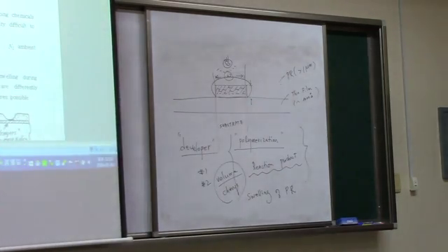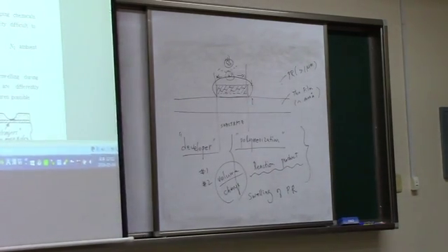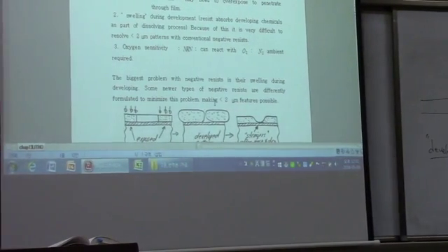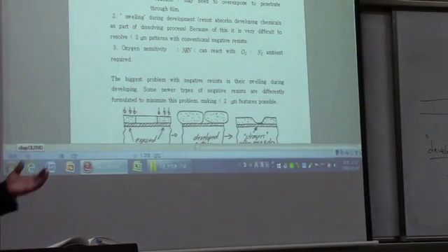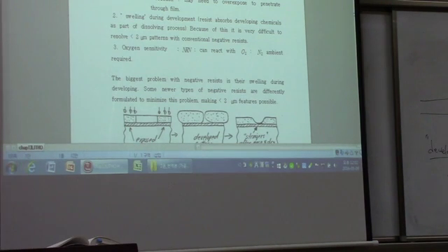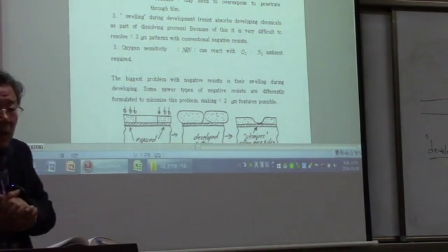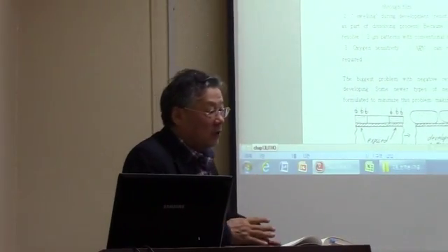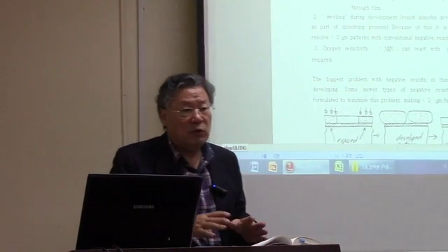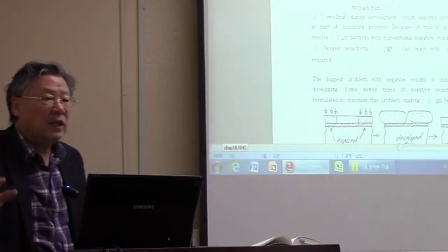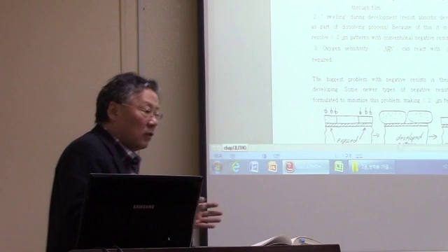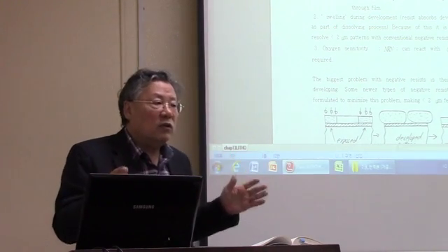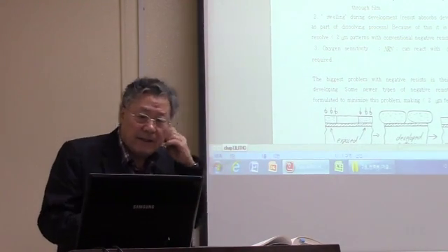And those two things are typical disadvantages of the negative photoresist, even though the negative photoresist has many advantages, like good throughput and things like that, okay? So, in modern VLSI, for the high resolution devices, the negative photoresist is not going to be used, because we cannot sacrifice the resolution. In the modern devices, the resolution is the most important thing, okay?